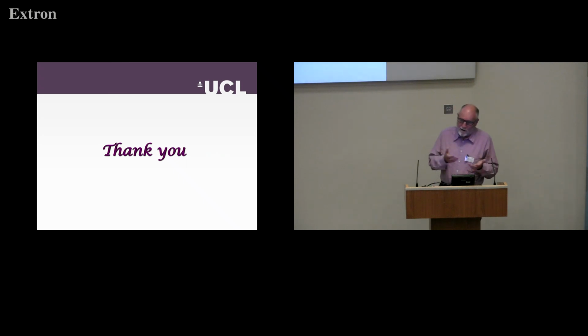So the concept of fracture mechanics and fracture toughness measurements is you put a notch in the sample, a notch which is bigger than any natural flaw, but it's your notch and you've put it in, so you can then calculate how the fracture propagates from that known flaw size of a known orientation. So you get a more fundamental understanding of the resistance to fracture of the material.